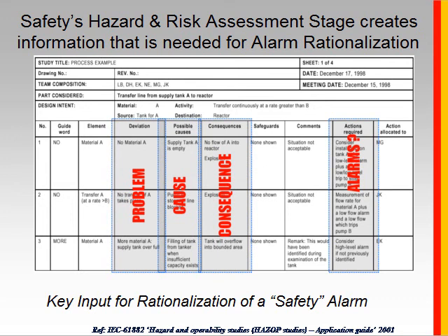One of the things that you're going to see is that the process we are using here is we are looking at the documentation for the plant and understanding the process to figure out what points should be in alarm and why. That's the opposite of the work practice that occurs for many projects, which is often, if the DCS provides all these alarms, let's enable them all and give them appropriate limits or set default limits.